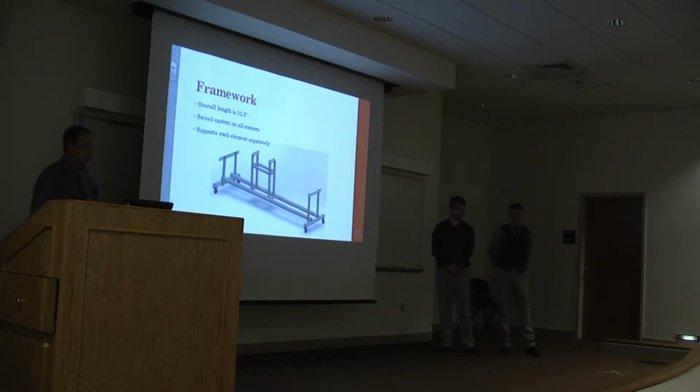Now the framework is what holds each of the different elements in place independently. We have the contraction, the test section, and expansion section, the test section being the most critical. Overall, it is 12.5 feet long, and then we have solo casters at each corner for maneuverability.